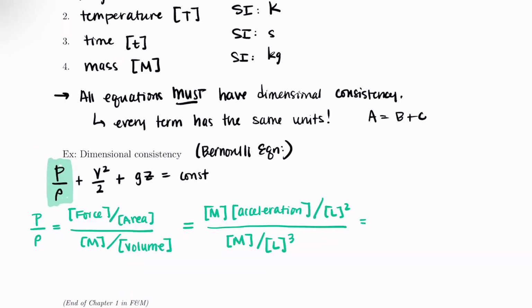So the last thing that we need to do is sort out acceleration. For acceleration, I just like to remember the unit for acceleration is meters per second squared. So that's a length divided by time squared, right? So just be careful with the t's. Lowercase is for time, uppercase is for temperature. All right, and now I have everything in terms of our primary dimensions. So I'm going to rewrite this out.